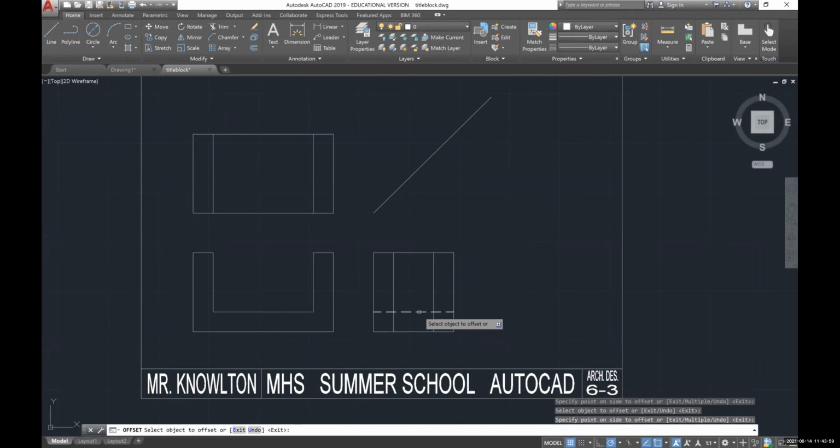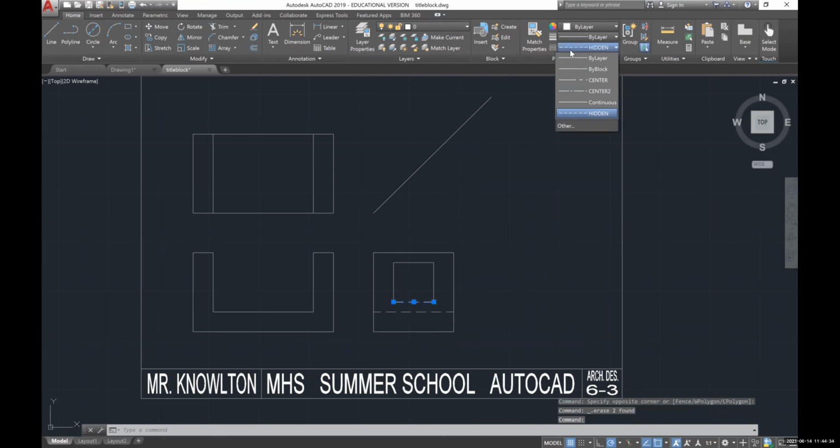So 1.5 minus 1 inch for the thickness of the window is 0.5. Half of 0.5 is 0.25. So I'm going to offset 0.25. Offset this line down, and the dotted line up. So right here's my window. Now I just have to trim. Delete out these. Change this back from a hidden line to by layer. Escape. And there's my right side.